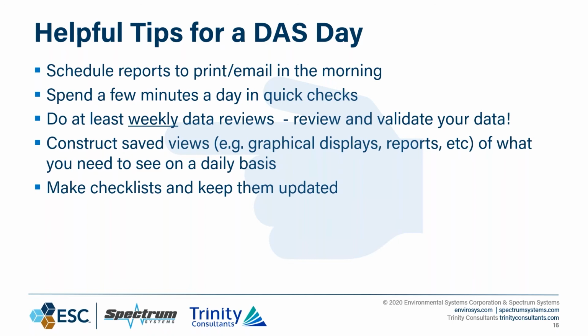And the other thing is in Part 75, I'm seeing a lot more petitions to the EPA for utilizing Coriolis-style meters for fuel flow monitoring. So if you're going to be doing the QA checks and the tests, you need to understand whether or not your site has any petitions out to the EPA, and they've elected to use a different type of technology that might not necessarily be spelled out in the regs.